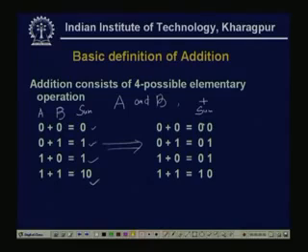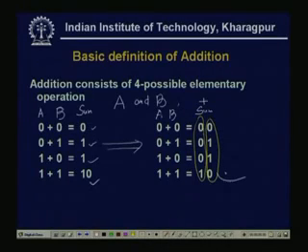There are 2 bits, one is the LSB and the other is the higher bit. If the sum is realized by only 1 bit, then the LSB, 0 1 1 0, I can define as my sum bit, normally denoted as S. And this 0 0 0 1, we call the carry bits, normally denoted by C.